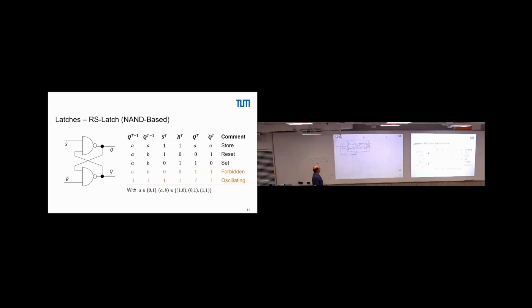So we had here already the case that if you go, for instance, from reset to set, then you have here something depending on the set and on the S bar and the R bar. So we want to reset from a set state. Then we put the S bar to 1, the R bar to 0.